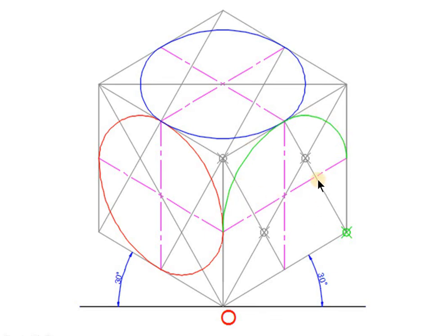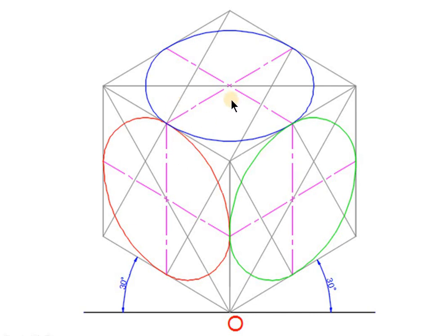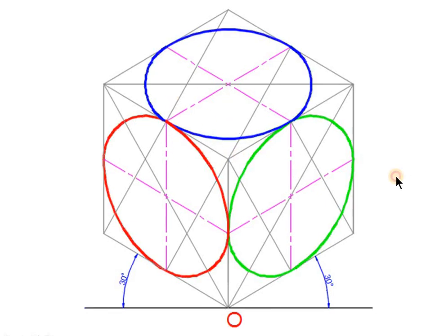So when you want to draw a semi-elliptical portion, then that means what? You have to select any 2 centers with which you can complete the appropriate semi-elliptical curve like this. You can use a single center for completing the fillet of the isometric object, 2 centers for semi-circular or semi-elliptical curves, and then 4 centers for a complete ellipse, like elliptical portions on 3 isometric planes.